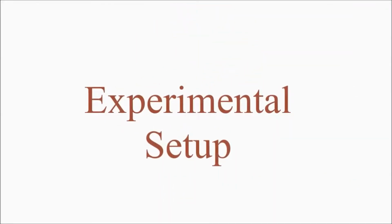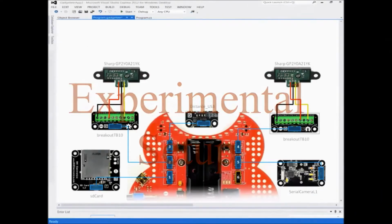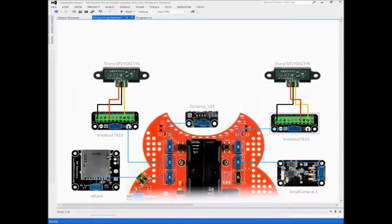Since one single sensor is not capable of doing the task, employing multiple sensors rises in importance. The mobile robot used in this work utilizes 6 different modules: 2 infrared reflective sensors, 2 infrared distance measuring sensors, a serial camera and ultrasonic sensor.